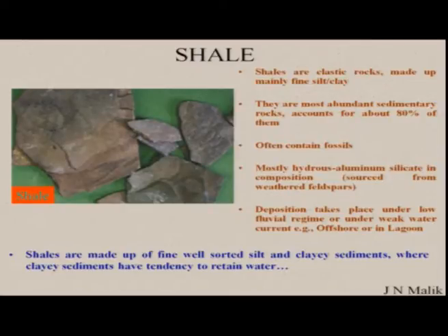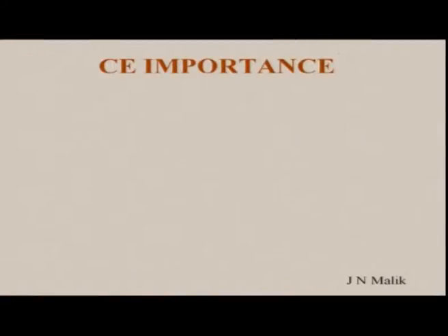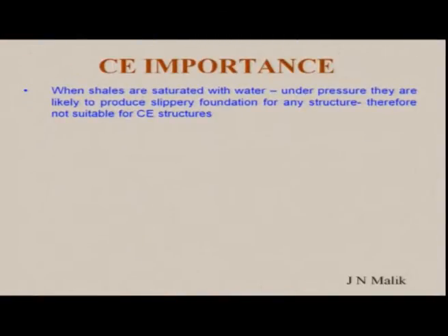So, they have the capability of retaining water, which can result in the weakening of this type of rock, particularly shale. If you come across shale, it is not very good to put any civil structure on it, because it can hold water and result in slippage along the planes. When shales are saturated with water, under pressure they are likely to produce a slippery foundation for any structure. Therefore, they are not suitable for putting any civil structures on.